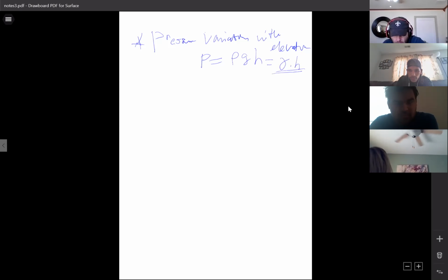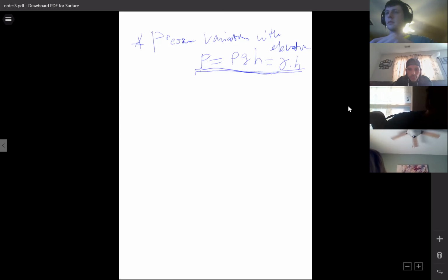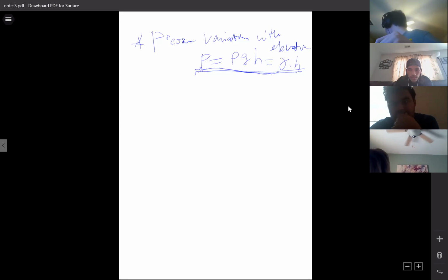Let's use this equation in our class. So that tells the story. Look at the equation. You're a future engineer, right? A future engineer always tells the story based on the equation. A lot of you don't have that mentality yet, but that's the correct mentality as an engineer. Everything you say based on the equation, then it's safe. So look at this equation. That tells you a lot of stories. P equals gamma times h. Gamma is the property. It doesn't change, it's a constant property. So basically, in hydrostatics, pressure only changes with elevation.